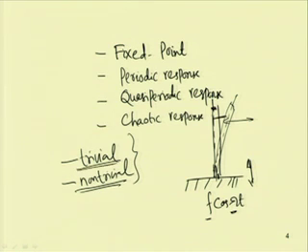That means the response is 0. For the response to be 0, the vibration will be a trivial state vibration, and when it moves to a particular distance and vibrates at that point, that will be a non-trivial state of response. In case of the trivial or non-trivial state of response, if the magnitude is fixed, then it will be a fixed point response, and if it varies periodically, then it will be a periodic response. If it varies in a quasi periodic manner, the response will be quasi periodic, and the response may be chaotic also.